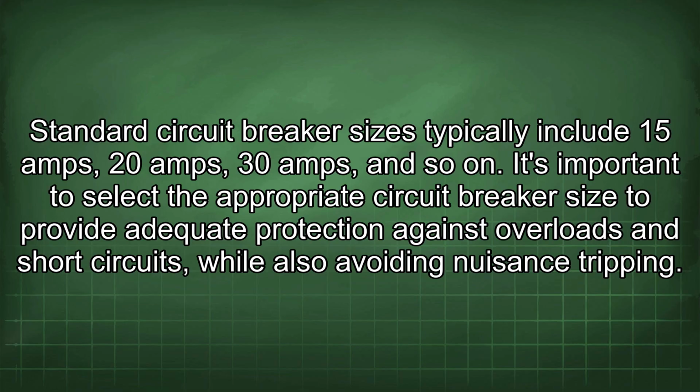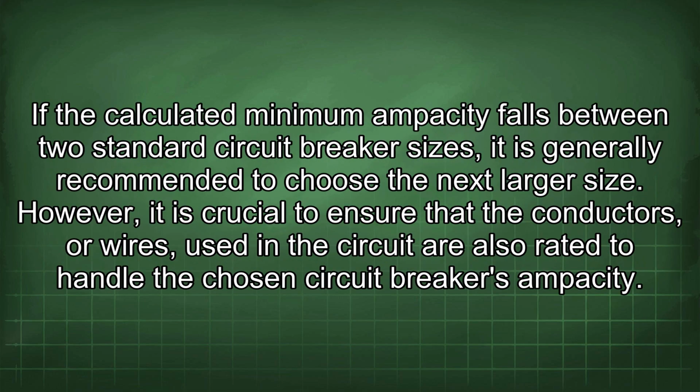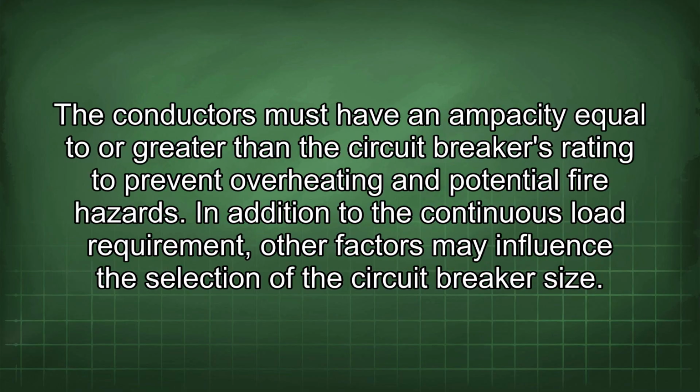It's important to select the appropriate circuit breaker size to provide adequate protection against overloads and short circuits, while also avoiding nuisance tripping. If the calculated minimum ampacity falls between two standard circuit breaker sizes, it is generally recommended to choose the next larger size. However, it is crucial to ensure that the conductors, or wires, used in the circuit are also rated to handle the chosen circuit breaker's ampacity. The conductors must have an ampacity equal to or greater than the circuit breaker's rating to prevent overheating and potential